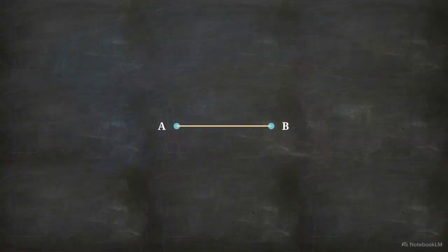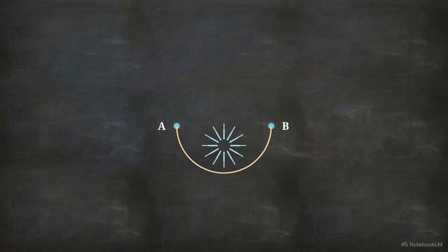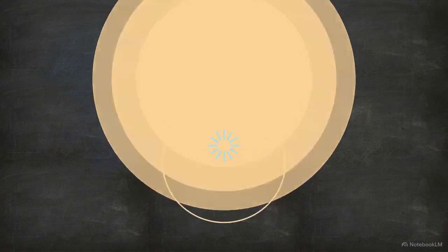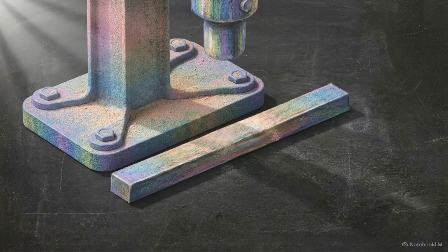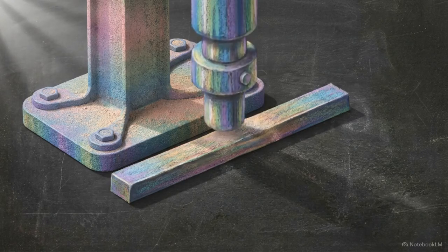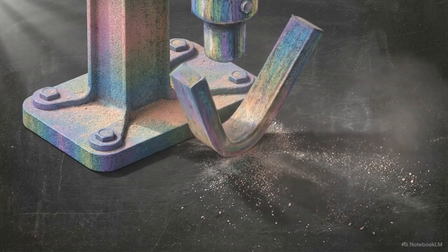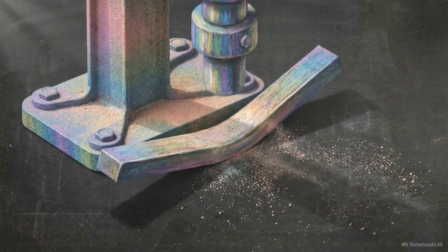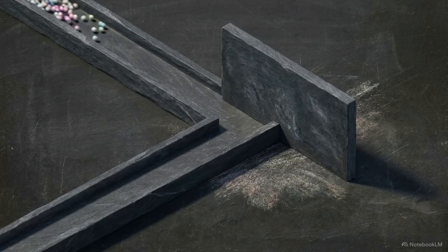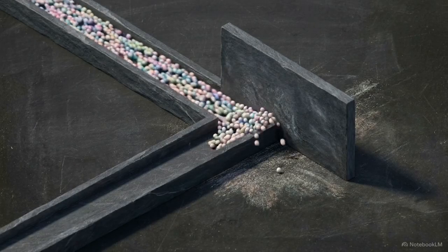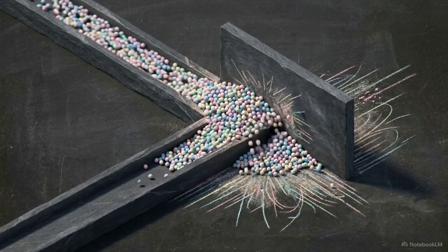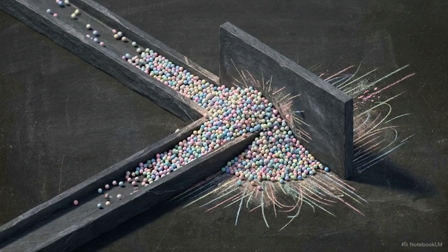As long as the driving force is maintained, a single pinned segment rapidly repeats this exact process, emitting hundreds to thousands of complete dislocation loops every single second. This continuous multiplication permanently feeds the Taylor-Orowan equation, cleanly explaining how rigid materials manufacture the density required to survive extreme strain without fracturing. Generating 1 billion dislocations is only half the equation. Those defects must travel to cause deformation. But the interior lattice is densely packed with obstacles.